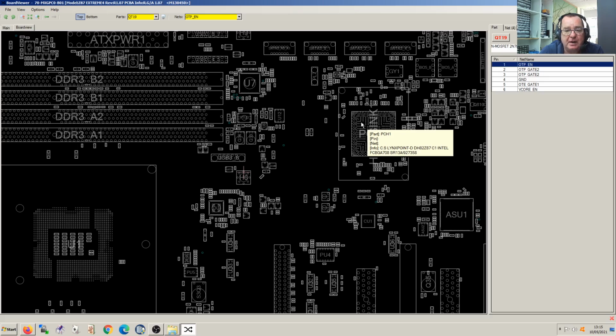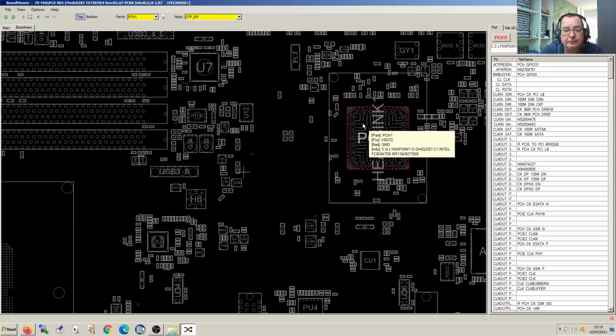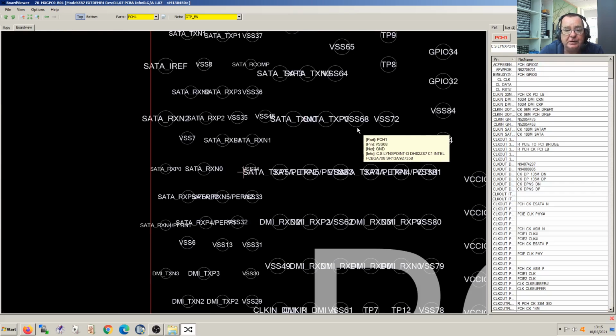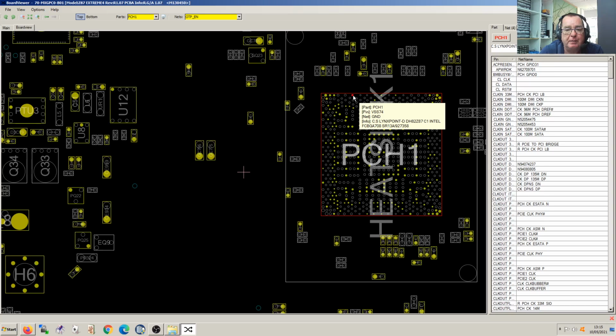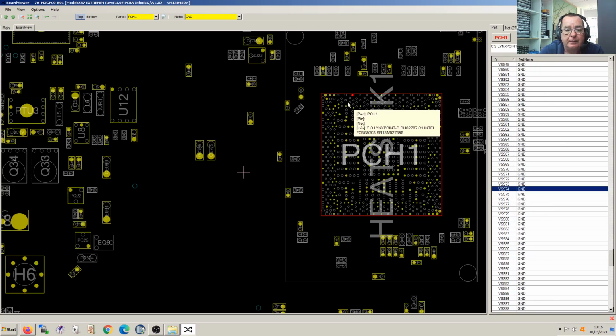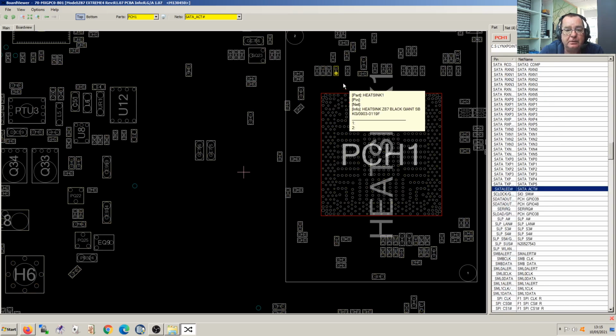This is a PCH, where obviously these connections are underneath the chip, and you can't get a meter probe on them if you're interested in them. But if you click on the connections, you'll often find, look, in this case, this connection here, SATA LED low. See the little hash bars? That signal is low active, yeah? SATA LED low. And although you can't probe that, you can probe this component here. This is where it goes to.